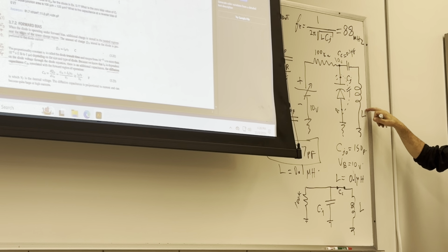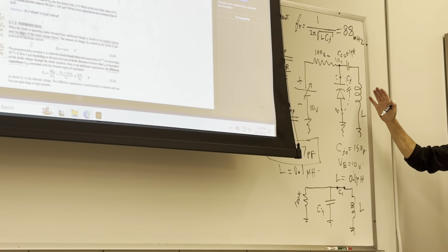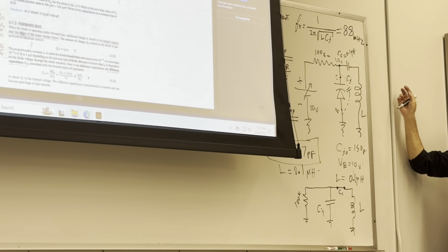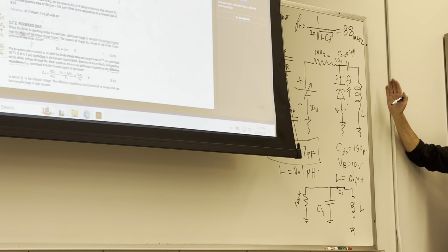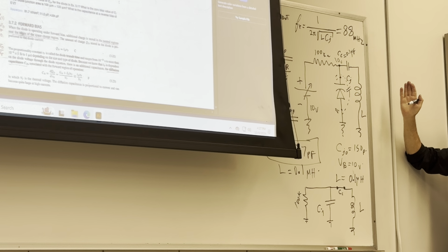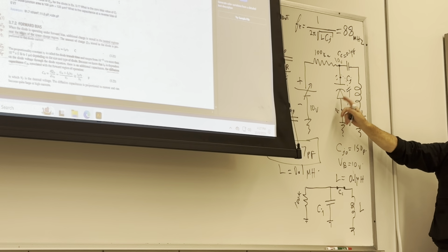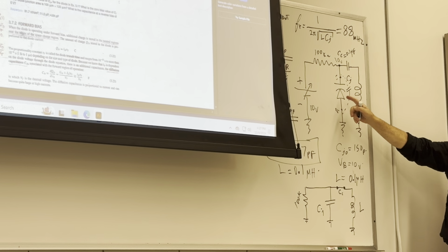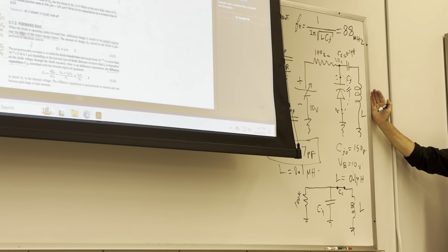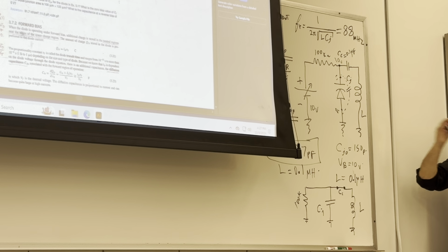And even if you cannot get to that corner that we want, it's possible. Inductor switching. You put another inductor in. So you've got an analog switch in here that brings a second inductor, range. It's called range selector. They go bands, and then tuning within the bands. Tuning within the band is done with the capacitor, with the varactor. Band change is done with the inductor.